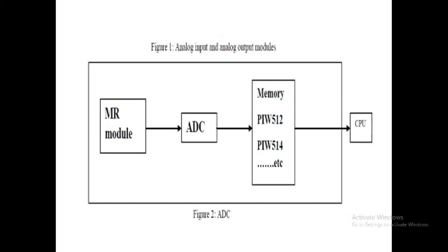Because the value of M90 is 0, it processes the analog input as a unipolar number, which converts this integer value to a real value, as the PLC reads only real values, and FC105 scales the real number to a value between 0.00, that is parameter LO_LIM, and 10.00, that is parameter HI_LIM.